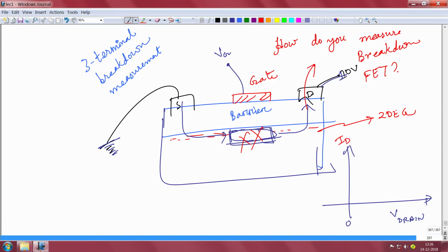Where will the current come out from? There are two sources. One source is that it can come out through this substrate, which is called the buffer, or you can call it the substrate, by the way. This substrate should not be able to leak. Whether it is a MOSFET or a HEMT, if it is a good substrate, it should not leak, but if it is a leaky substrate, it will leak.